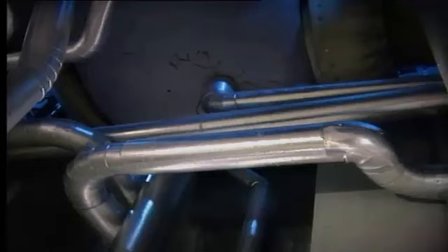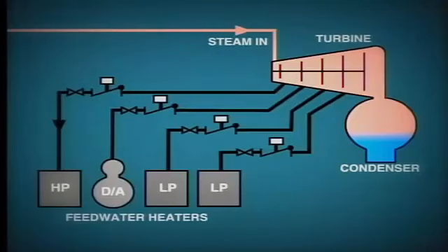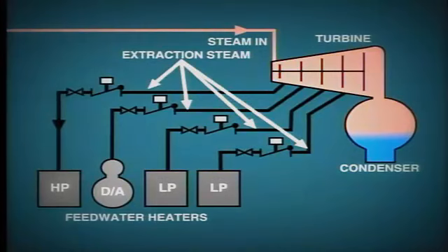We have already mentioned that steam is extracted at various points along the turbine and used for feed water heating and perhaps for industrial process work. Here is a simplified arrangement where we show just 4 stages of feed water heating and therefore 4 extraction lines only. The extraction steam lines operate at much lower pressure than the main steam.